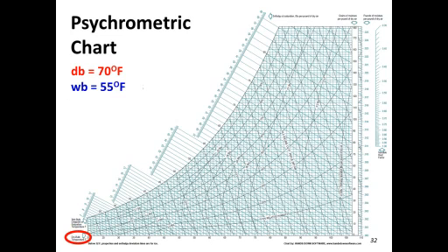The dry bulb temperature is indicated on, if you remember back to elementary school, the x-axis. So these are dry bulb numbers on the bottom. And this indicates that the x-axis is dry bulb. So 70 degrees dry bulb is what the young lady determined. At the bottom of the 70 red line is 0% relative humidity.